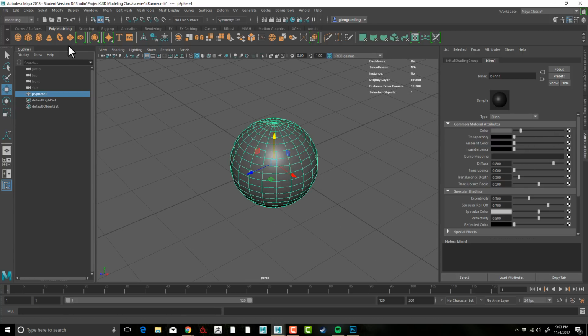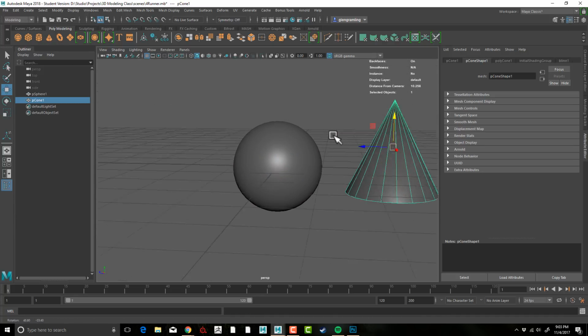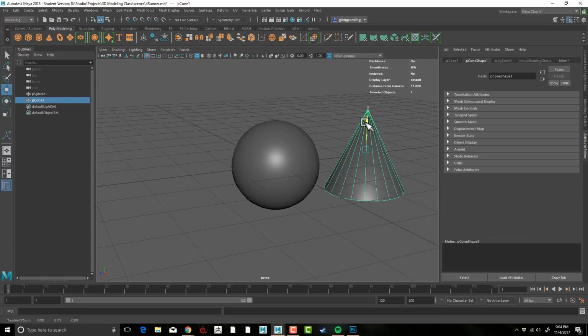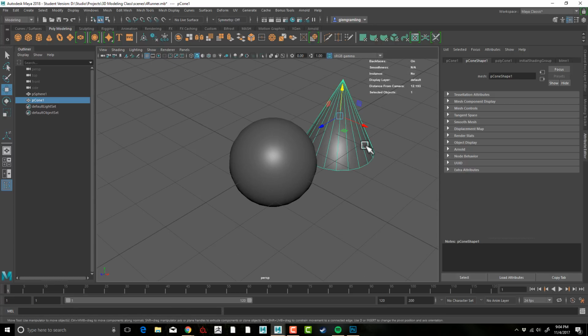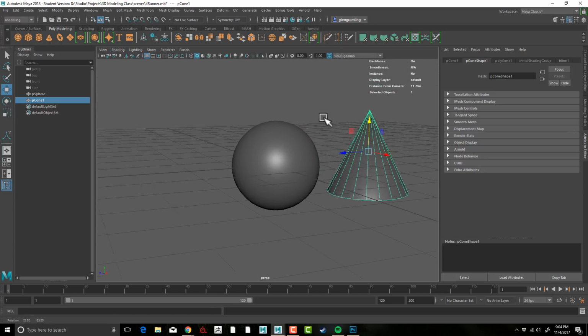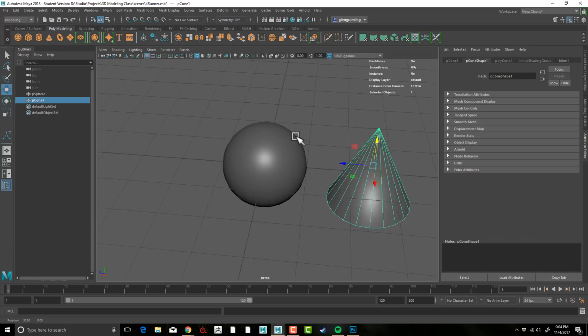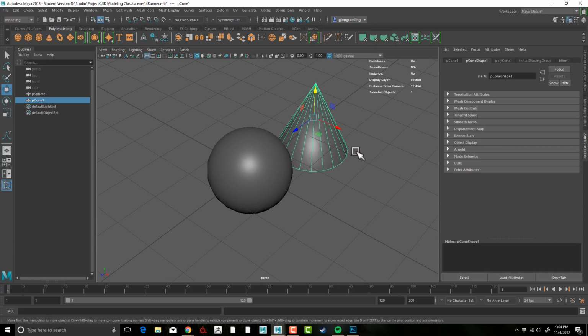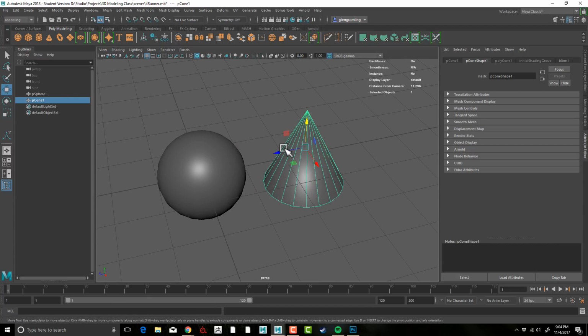Any new shape that I make will also have that Blinn applied to it. This is really useful for patch modeling where you're constantly creating new objects. This way they'll all have that Blinn shader applied whenever they're created, and not that default Lambert 1, which can be kind of annoying.